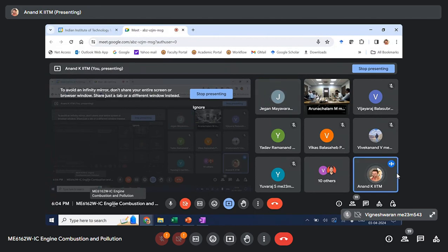No, I don't know why you want two references here. My suggestion is you can go with one reference like we discussed. For 4-stroke and 2-stroke, the difference is you have one cycle completed in 2 strokes of the piston. But the processes are combined in a 2-stroke. For example, when the piston moves up, you will have intake happening on the crank side and compression happening on the piston side. Correct, sir. And near the end of compression, the combustion will get started, depending on whether it is SI or CI.